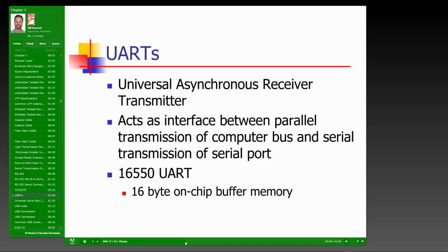So in the communications component, whatever that happens to be, the modem, network cards, this particular technology, I believe, is only applicable in the modem environment. The modem uses a UART, Universal Asynchronous Receiver Transmitter, and it's basically a buffer. Think of a UART as a buffer. So as all this data comes in very quickly from the computer side of things, and it's trickling out slower on the serial side of things, then the UART is the buffer that can hold all the incoming data and then properly flow it out to the serial port using the modem device.